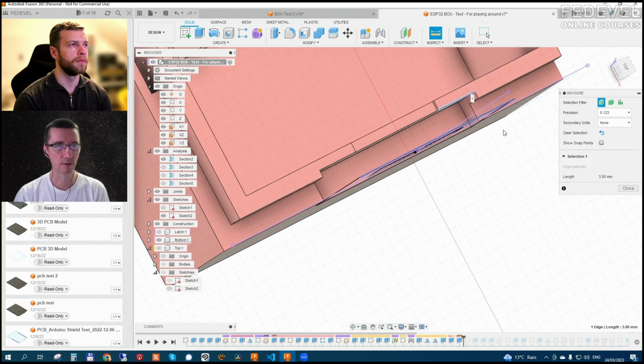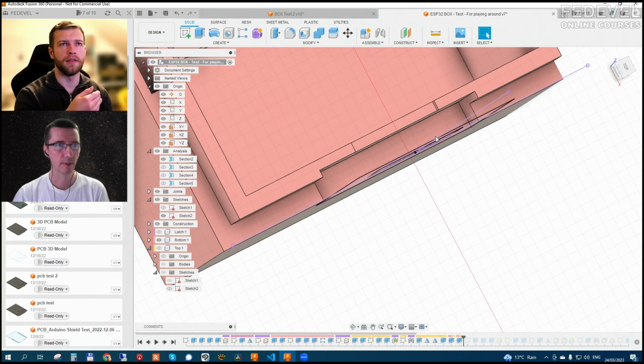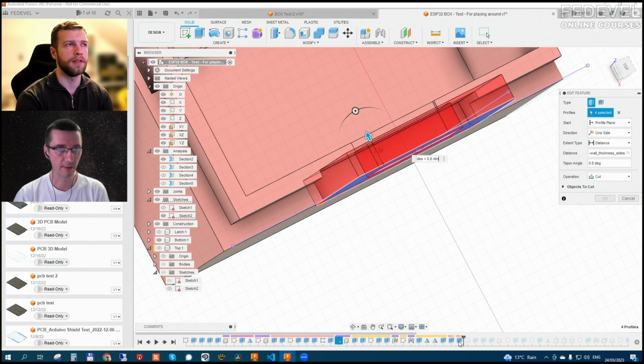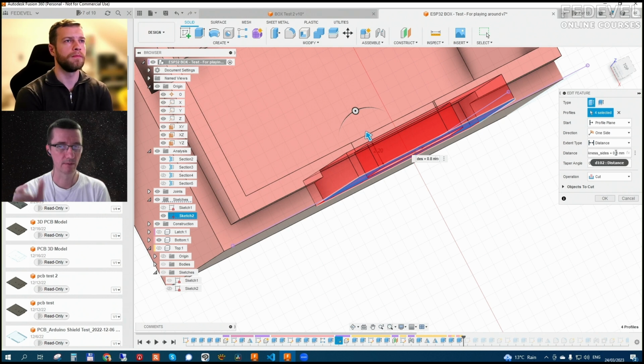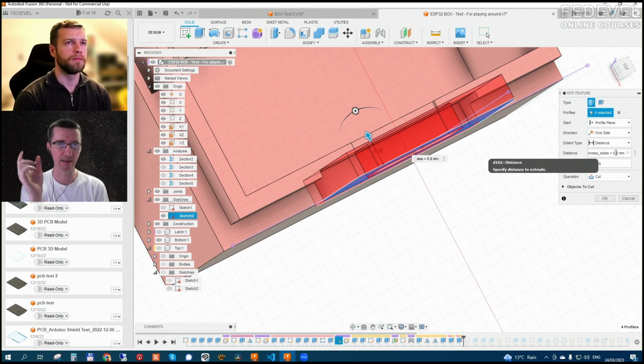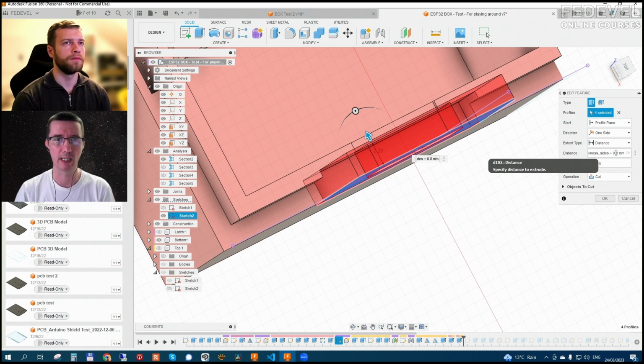So for that cut you did to that surface, minus the distance. Yeah, I think wall thickness plus 0.8. That's what I just specified directly. I think it's like 1 millimeter maybe what you have there. So I just put there 0.8 because 0.4 is the nozzle of my 3D printer. So it's like 2 lines, 0.8. Okay.